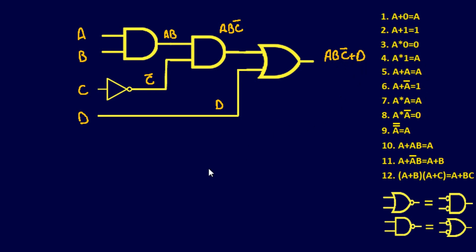Alright, final equation. So now, let's see if we can do our method here and actually see if we can come up with a nice clean answer. Well, I want this to turn into a NAND gate. So I'll put bubbles here, which means I got to put a bubble at this end too. And then a bubble right here. So that's already 2 NAND gates knocked out. Well, let's see if I can do that again. Well, I want this to be a NAND gate. The only problem is I got to add a bubble here too.